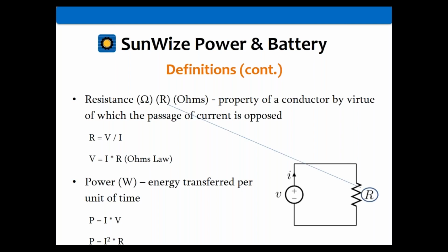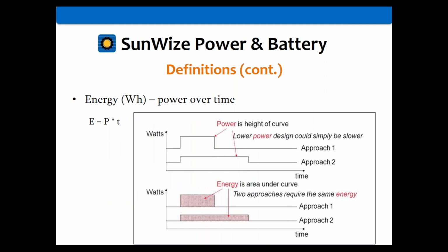Okay, there's a little symbol for that. Okay, energy, for which watt hours is one of the common units. There are other ones as well, but that's the one that we commonly use in electricity. And you'll notice that energy is power over time. The formula is energy equals power times time. So that's why you have watts times time, which is hours. It could also be watt seconds or watt minutes, but that's not normally how you think about it.